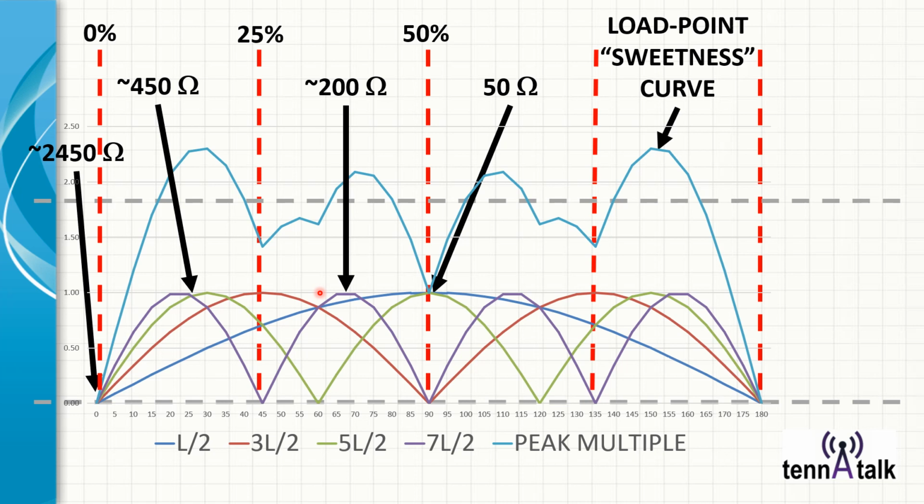Where is that curve? Well, guess what? It's the green curve. So follow the green curve. I have one node lobe, another lobe, and I have a third lobe that makes three nice lobes that fit within the same 40-meter half wave antenna dipole.